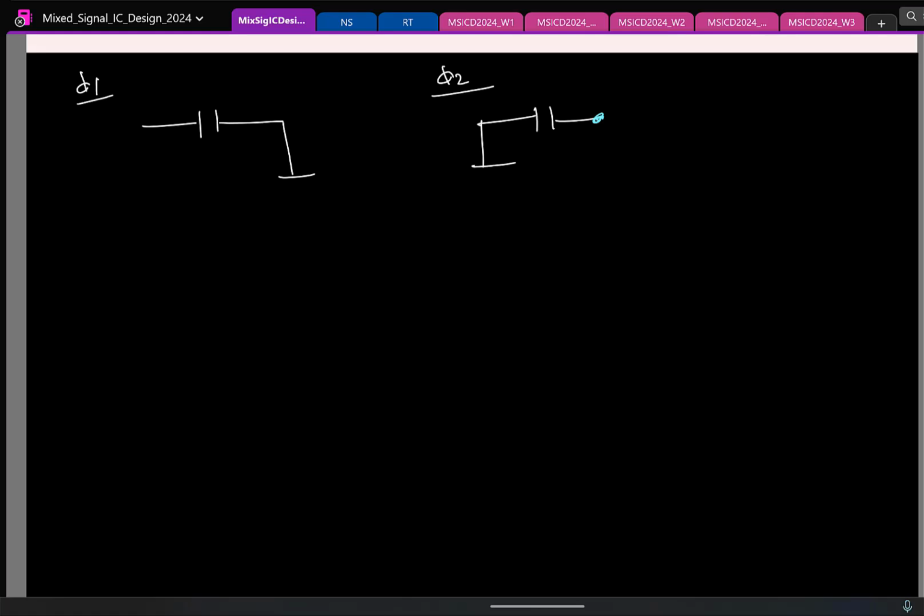What is used as buffer? Common source, common drain, common gate. Huh? No, common source is an amplifier, right? You think about it. Okay. Yeah, you can use something, but the point is, if you use a buffer like that, it turns out, without going into details, it is more non-linear. We don't do it in practice. So.